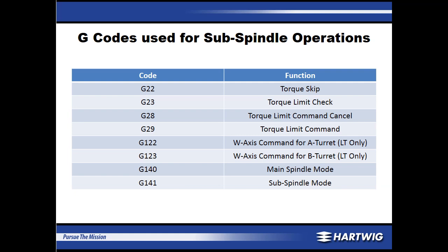and then alarm out saying you've put too much load on the ball screw on the servo motor. We can't feed any further. You don't want to. This will prevent damage in the machine, such as rapiding a subspindle into a part at 100%. It'll just bump the workpiece, throw an alarm. Okay, I need to back off a little bit or figure out why things aren't lining up.